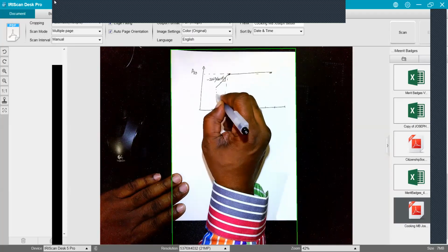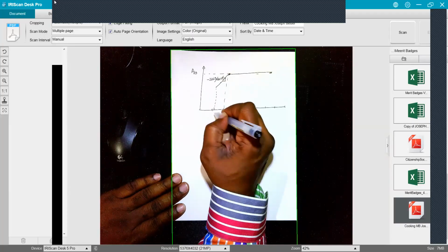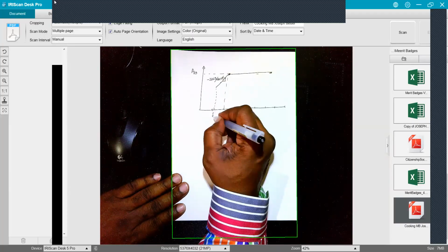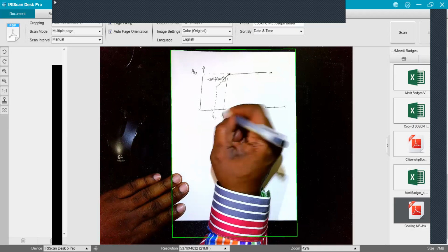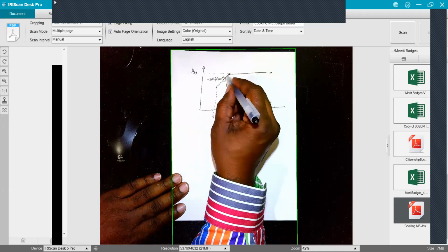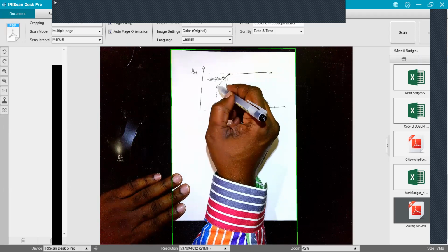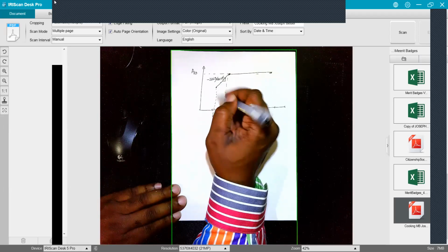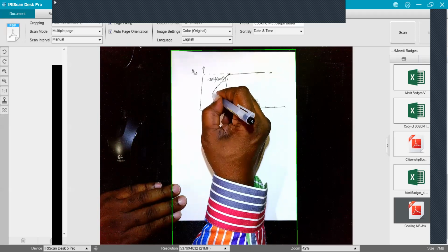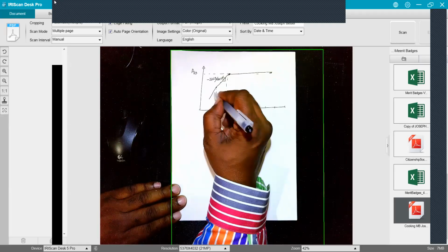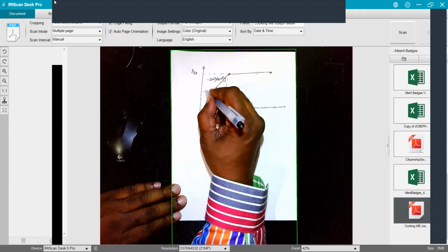And then we have another pole that shows up. We call it FL2. And it adds to this slope another 20 dB of roll off per decade of frequency. So it'll change the slope like this. So this is now minus 40 dB per decade.